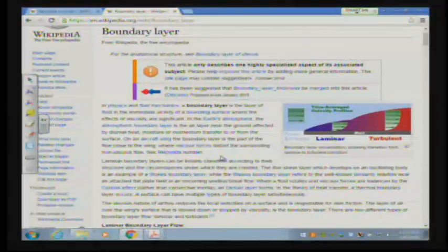And so we've also talked about the fact that with turbulent flow and laminar flow, the Reynolds numbers look significantly different. So you can determine whether you're in a laminar or transitional flow by taking a look at the Reynolds number. Now, when you look at the boundary layer, where those viscosity effects are important becomes a very important idea for how you model a fluid flow, and also for how you determine what are the most important characteristics of that flow for a particular application.